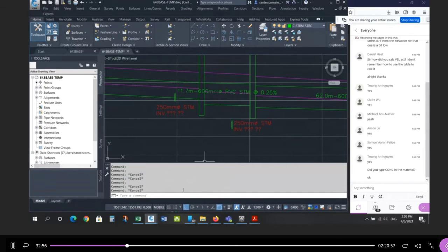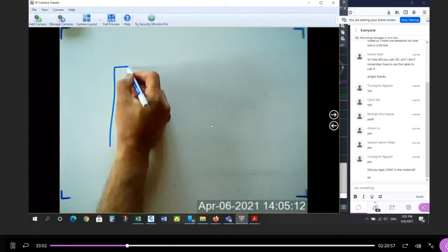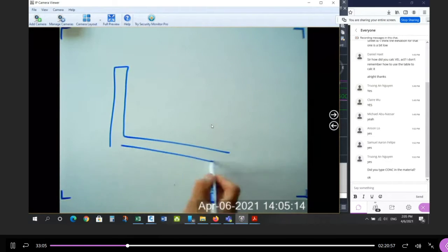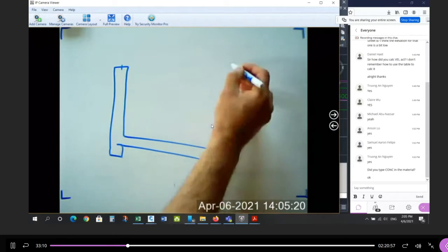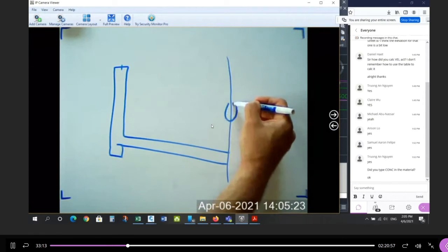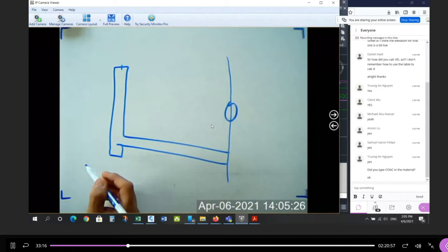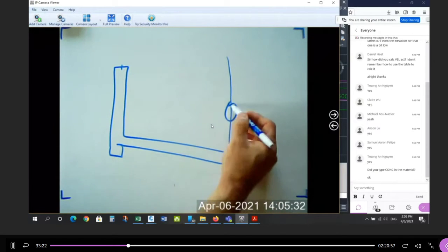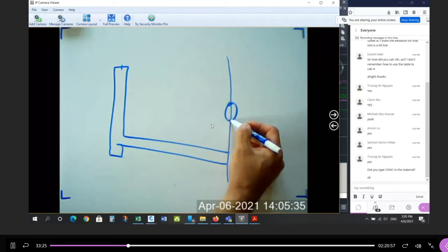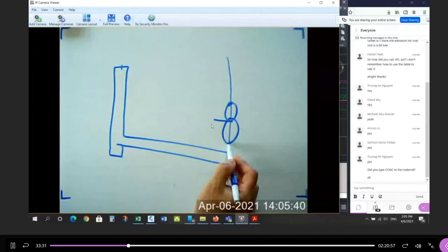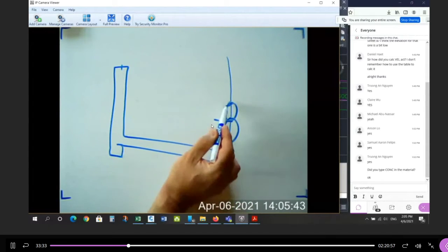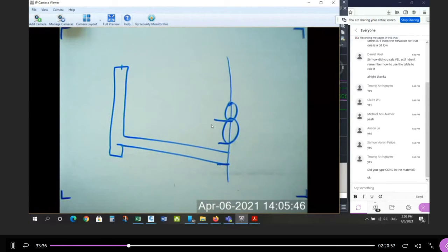When you raise these, what you're actually doing, let's go back to my drawing. Okay, so here's what we've done so far. I have a catch basin in the backyard. I have a pipe going to the street, right? It's calculated to the center. And then the street sewer, at the center line of the street sewer, the pipe's up here. Well, that's no good. So now I said, okay, I'm going to flatten the sewer. So instead of 0.5%, on some of the pipes, I used 0.25%. So now it took the design of the sewer, it made it bigger, but lower. So now what used to be the problem here relative to this is now this relative to this. Okay? So I've improved the situation by using a flatter gradient that's allowed.